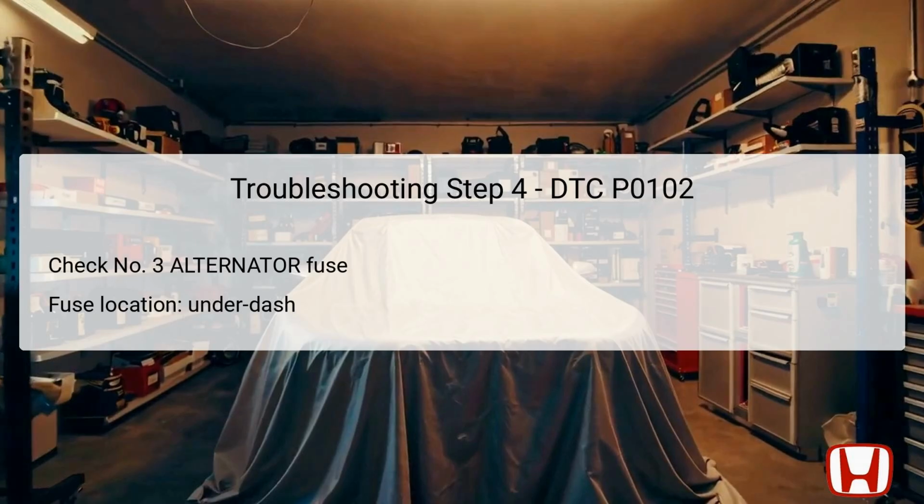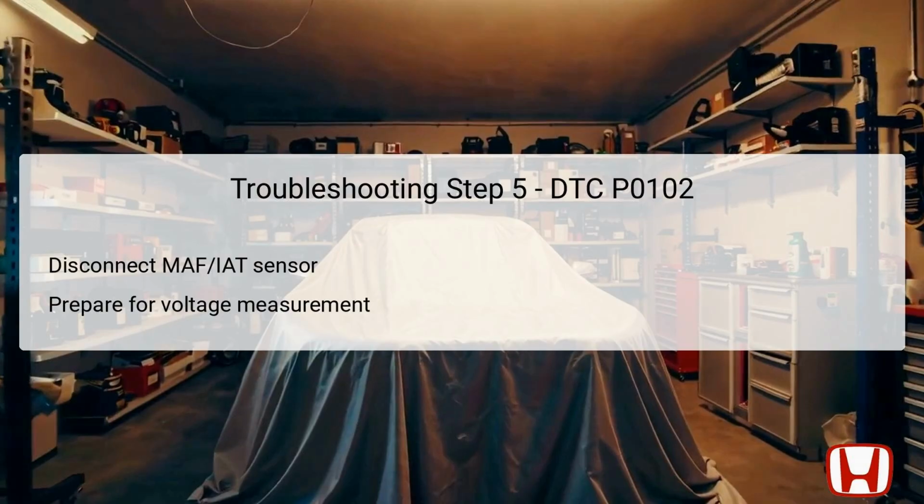Locating and checking this fuse can provide immediate insights into the electrical integrity of your system. The fifth troubleshooting step requires you to disconnect the 5P connector from the MAF sensor IAT sensor. This is an essential procedure before taking electrical measurements to avoid any interference that could lead to inaccurate readings. By isolating the sensors, you ensure that the voltage measurements taken in the subsequent steps directly relate to the sensor's performance without other variables affecting the findings.